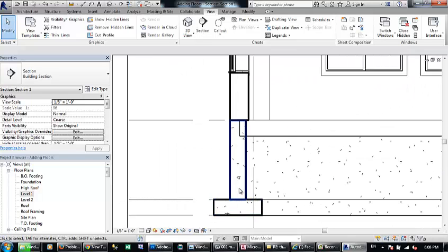Okay. Now, if we would have answered yes, the wall would stop here. This is the wall which is going from down to the level of the slab. If you click yes, the wall will stop here, because it will be merged and connected with the slab, the wall will stop here and the slab will extend here. So this is why I said no, in order for the wall to keep going until this level. Otherwise, this one will face a gap in the middle and it will fail. This is why I answered no.